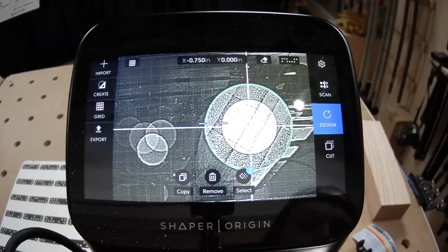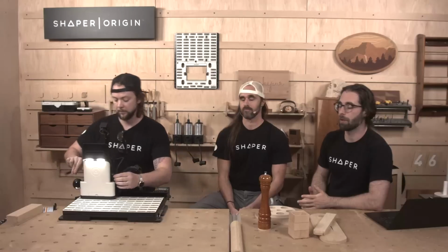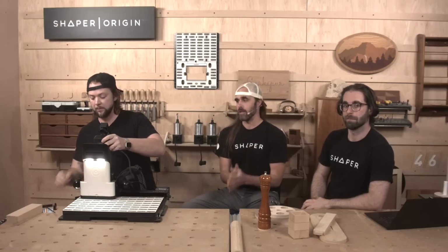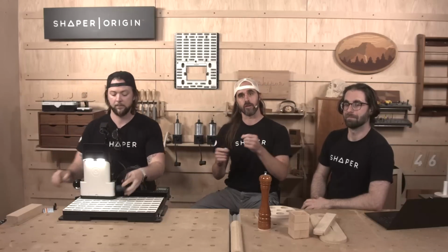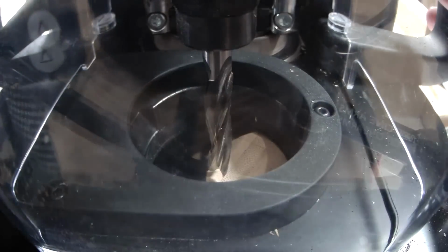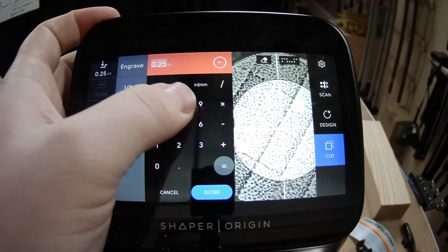If you want another tenon on this, you can just draw another circle at whatever size you want that tenon to be. Yeah, it's a really easy way to locate another shape on a circle. And so no longer do you have to find all the center points and do kind of complex math to figure that out. Just probe it three times, and you have everything you need to know.